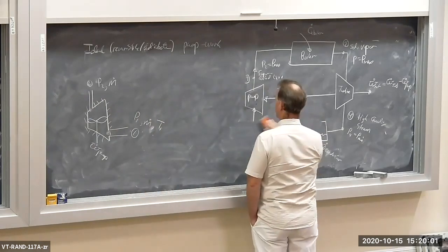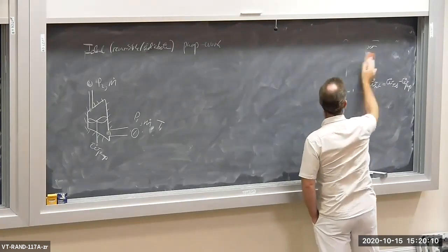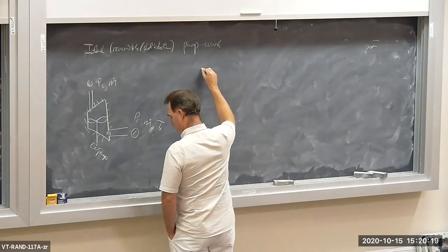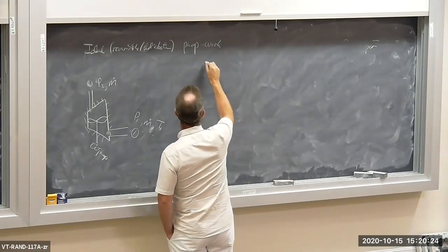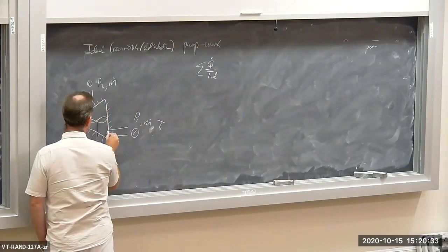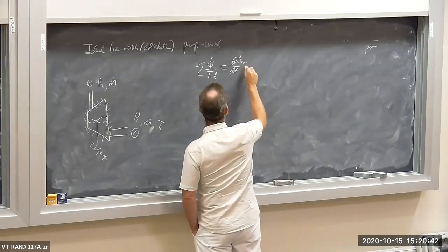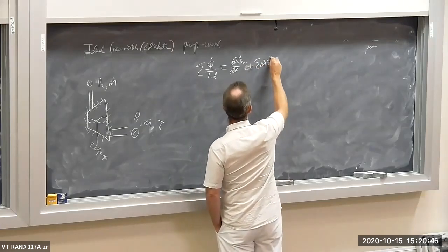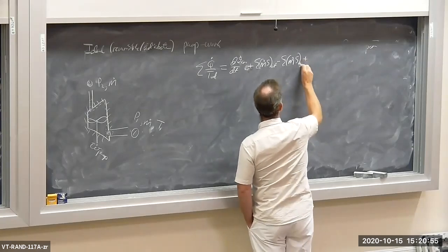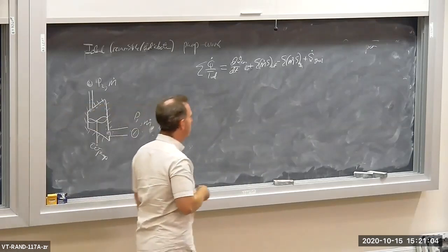Let's apply the entropy balance and see what we get with a reversible adiabatic pump. If your gut intuition is that it's an isentropic pump, you're absolutely right. So here, S balance, we got, so for an open system, we have the sum of Q dot over the interaction temperature. So my pump, here's my open system pump. So Q dot over T is equal to dS within my control volume dt plus the sum of the mass flows times S out minus the sum of the mass flows times S in, and then I've got S dot gen, okay? Open system entropy balance. So it's adiabatic.